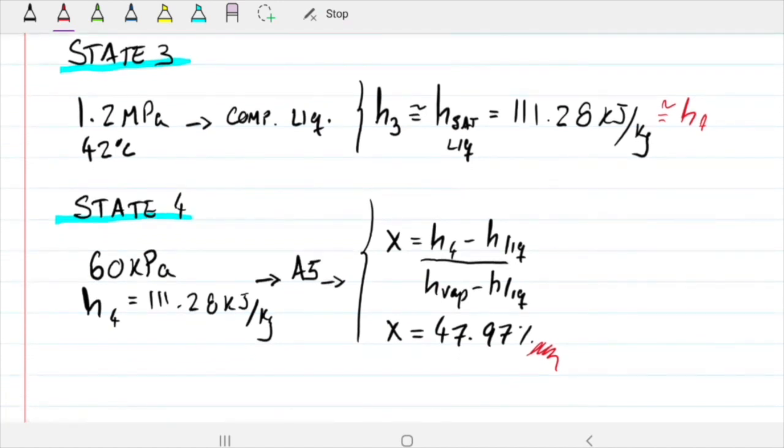So we know it's about 50-50, about 50% liquid, 50% gas. And we would expect that after the evaporator we have more gas state, right? So we would expect this gas state to increase as we're going through the evaporator. That's precisely the idea. Okay, so that's part A.